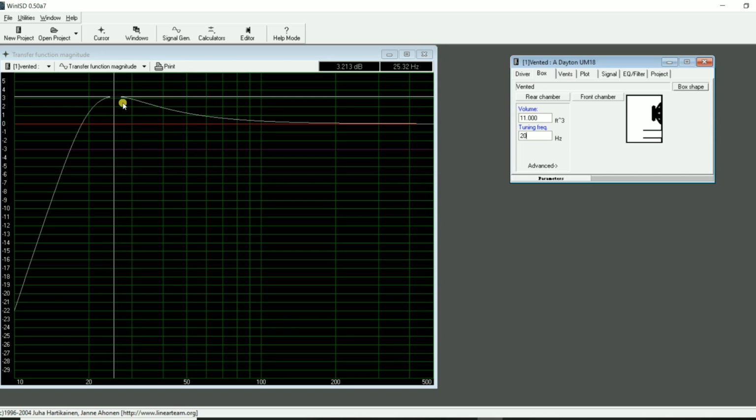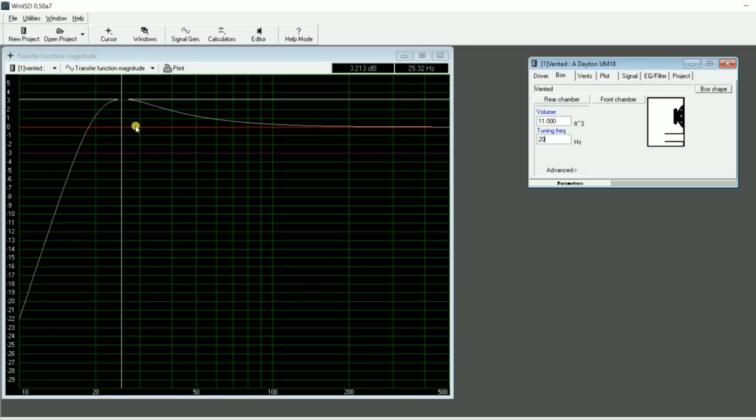Now in a room, you're going to have even more output here because of room gain, but then you're going to come back and EQ, so all of this extra output above your baseline is going to be headroom. And then you're also going to have a house curve. You're going to usually EQ in your response, or you're going to be using a loudness compensator like dynamic EQ. Yamaha also has a version of loudness compensation as well, and so they're going to integrate their own house curve into the subs, and it's going to be more boosting the further you are from reference. So this peak right here would actually be helpful because it's extra output in those areas where you're going to want a little more output anyway.